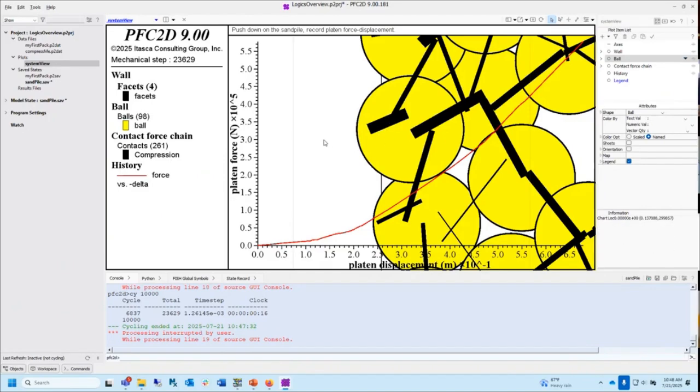And it's just going to keep slowly making it bigger. And in the world of PFC, we have to decide, once this centroid reaches the wall, what are we going to do? Because the fundamental assumption about how to get a contact between two objects breaks down. And so what we decide to do is once that happens, we remove the contact. It just disappears, which means there's a giant force right now pushing this guy towards the wall.